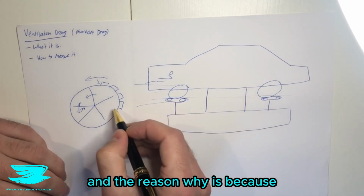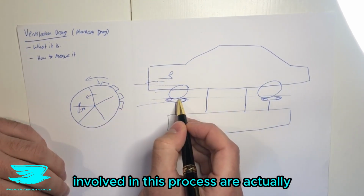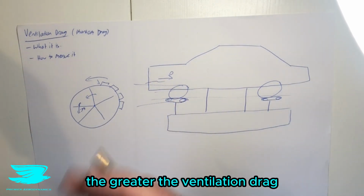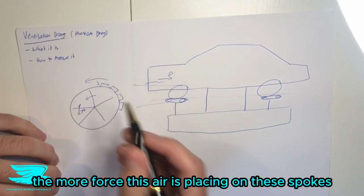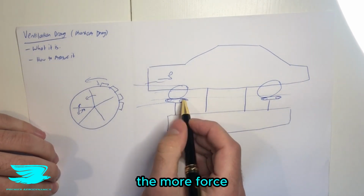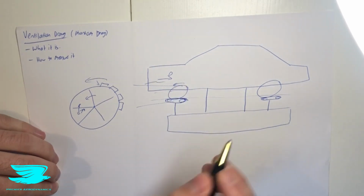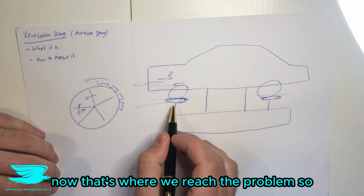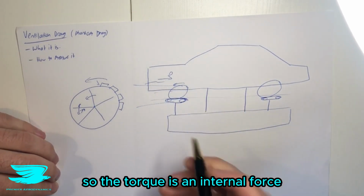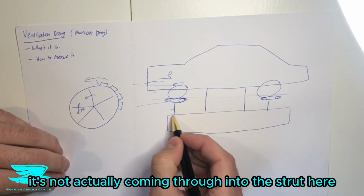And the reason why is because the forces that are involved in this process are actually coupled with the wheel drive unit. So the greater the ventilation drag, the more force that this air is placing on these spokes, resisting the wheel from moving, as well as the tread, the more force this wheel drive unit has to push along to rotate this wheel. Now, that's where we reach a problem. So the amount of force required to rotate this belt, so the torque, is an internal force. It's all within the wheel drive unit itself. It's not actually coming through into the strut here, into the load cell.